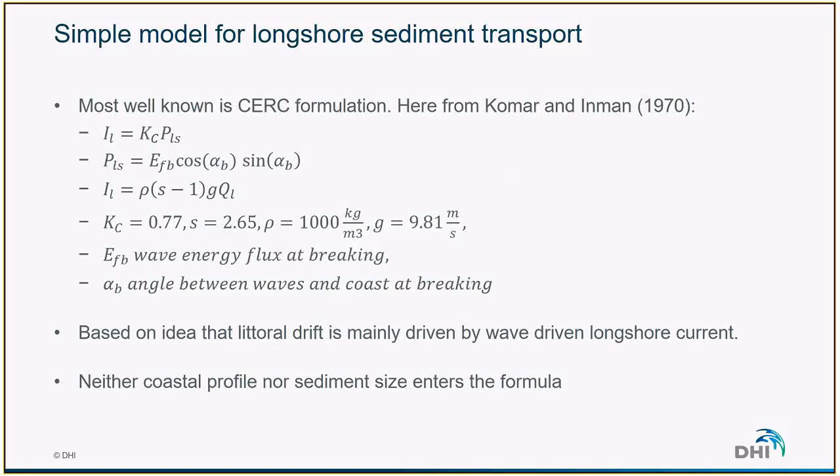So how do we calculate the longshore sediment transport rates? There are relatively simple formulas for calculating the longshore transport. One of the most known formulas is the CERC formulation. This formula relates the wave energy flux at the point of breaking with the littoral drift. It's based on the idea that the littoral drift is mainly driven by the wave-driven currents and not by tide or ocean currents.